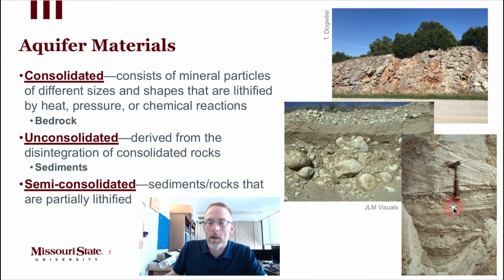I've done a lot of work on islands in the Caribbean on various projects, and I'm very used to seeing this where the bedrock's so young that it's poorly lithified, poorly cemented. So it's not quite consolidated into solid bedrock like we're used to seeing here in the middle of the continent in Missouri. And you can see here they've just drove the hammer right into it.